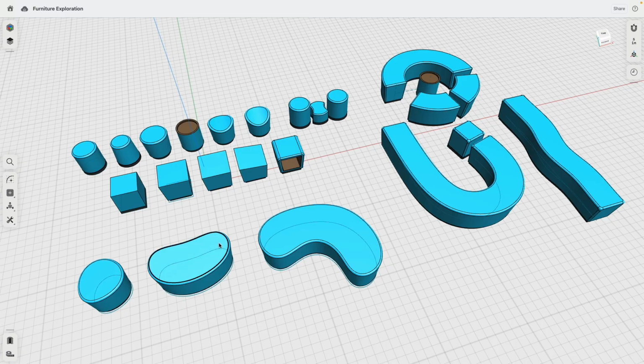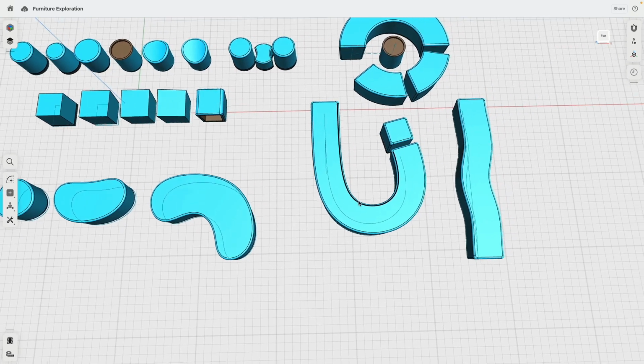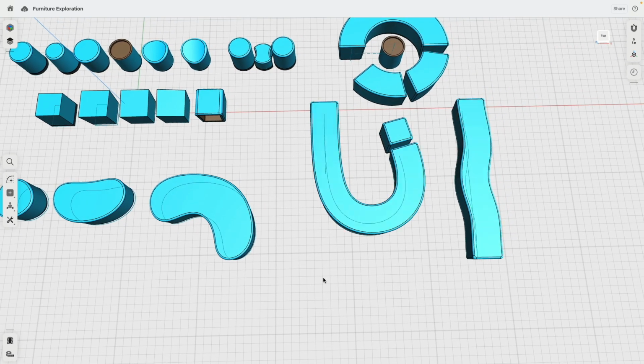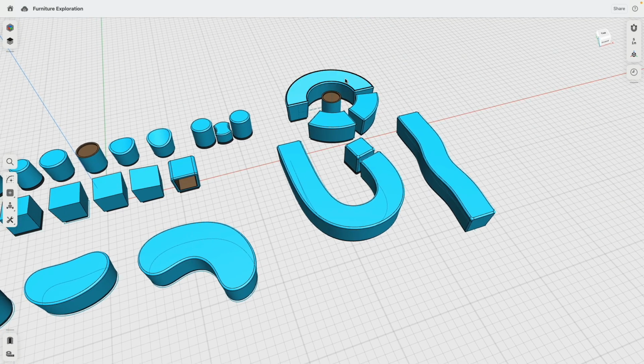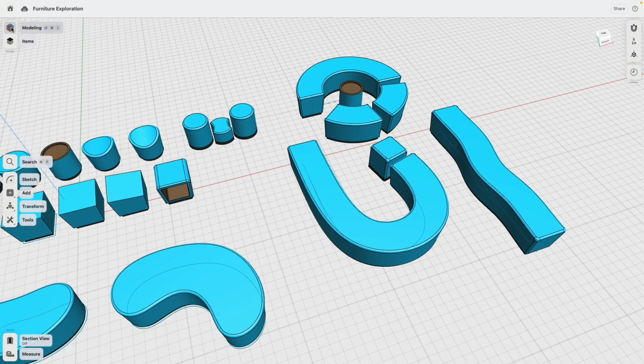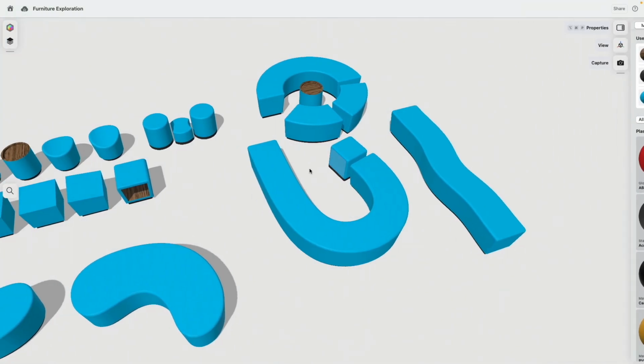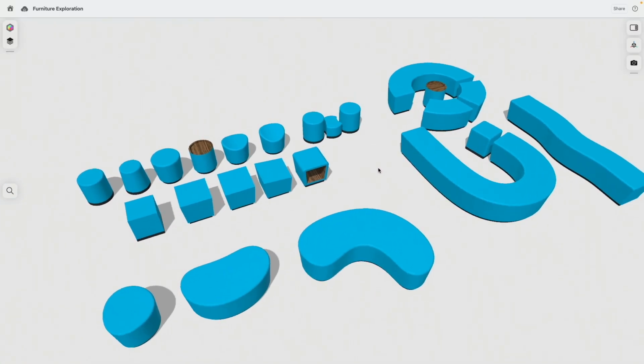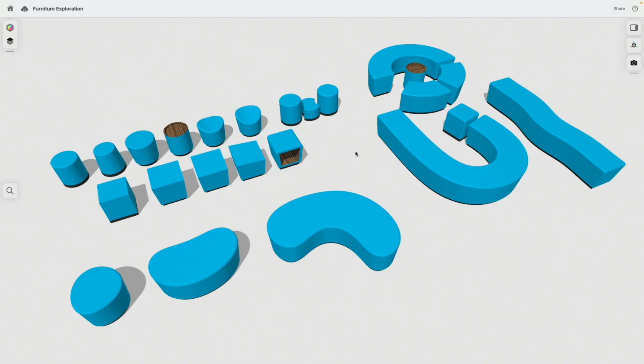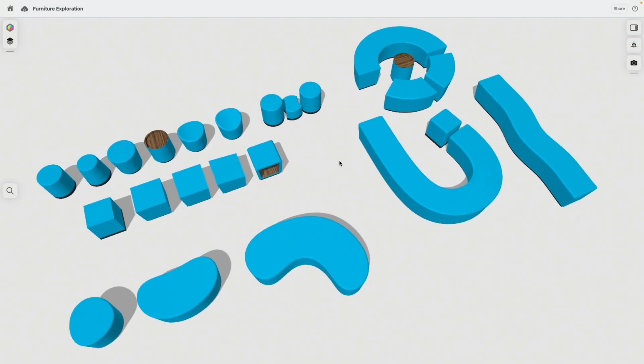We will also take a look into how we can create very organic shapes with the spline command. We will take a look at how we can use the sweep command to create these swept benches. And then we will finish everything with a revolve part. And then when we go into the visualization, now you will see that actually just by using very basic shapes and modeling commands, variation and quantity as a design principle, we already developed quite an interesting variety of different possible and valid design solutions. With all that said, let's do it.